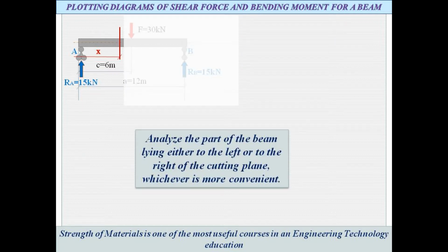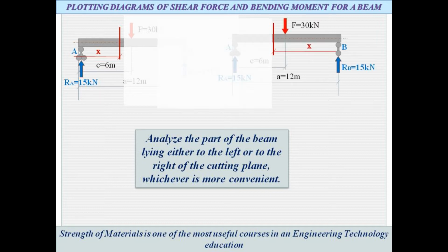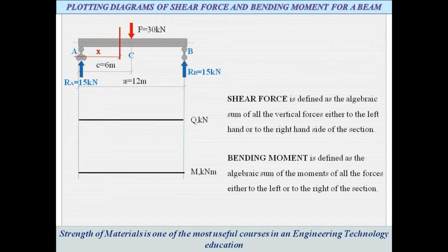Analyze the part of the beam lying either to the left or to the right of the cutting plane, whichever is more convenient. Shear force is defined as the algebraic sum of all the vertical forces either to the left hand or to the right hand side of the section. Bending moment is defined as the algebraic sum of the moments of all the forces either to the left or to the right of the section.